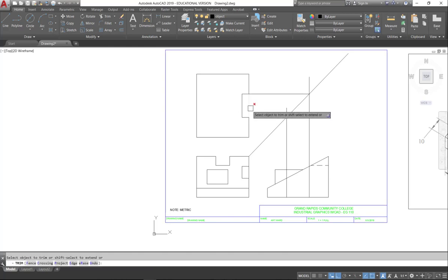Now this time, I'm not going to see any lines behind the notch because I'm looking straight down to the top. So I'll get rid of those. I want to get this little notch right here, so we're going to project that up. Instead of drawing multiple lines, I'm just going to copy from the end perpendicular.